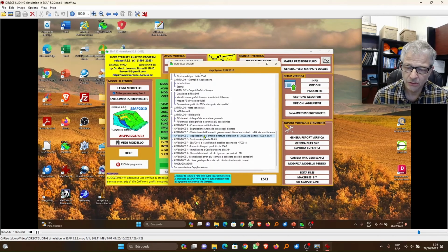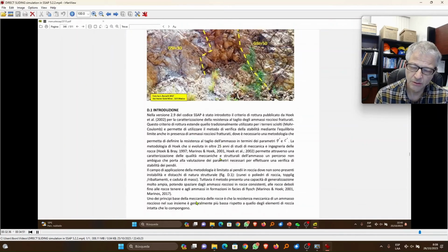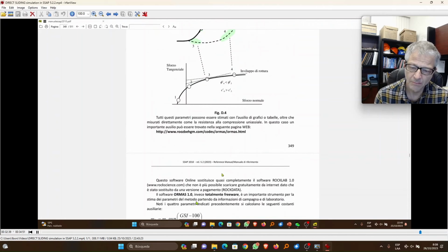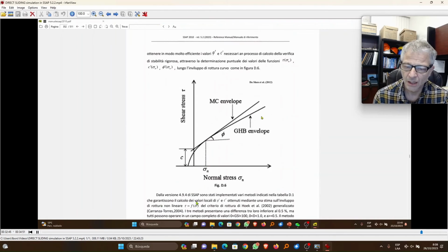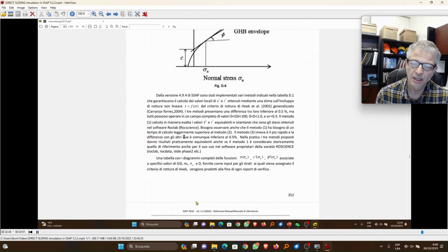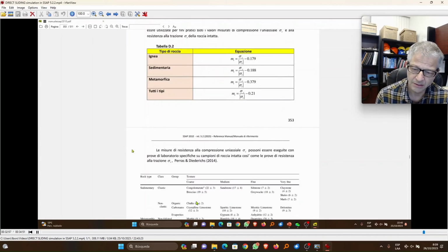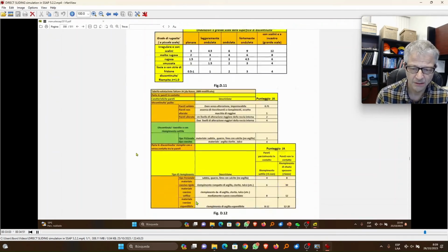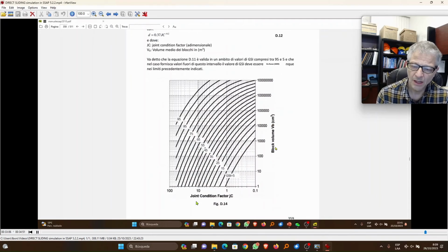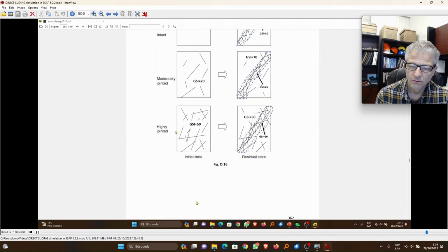In the manual, for example, we have the description of the rock mass characteristics that are considered, of course the GSI, both method and criteria, but in general the Hoek-Brown method with nonlinear methodology, with the possibility to define locally the parameters depending on the stress present, and also a criterion for GSI is described in the manual, so I invite you to read it.